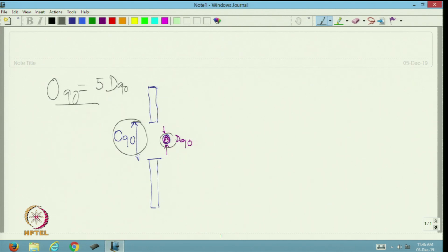The system here is that most of the particles we are allowing to pass through the hole, but gradually the particles larger than D90 will form a certain structure. Here the advantage is that the hydraulic condition is not harsh, that means the liquid flow will be slower with lower pressure.